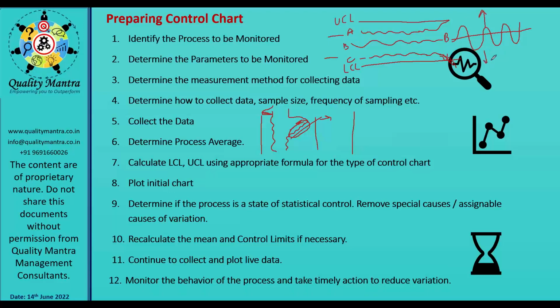So what you have to do is, your process variation should be low, it is close, the process should run very closely and the process should run in the center. Okay, only then the capability of your process, the CPK, we are not going into detail of the CPK basically, but just as we are on the topic, I am telling you the capability of the process will depend on where your process is running, the location, and with what variation.